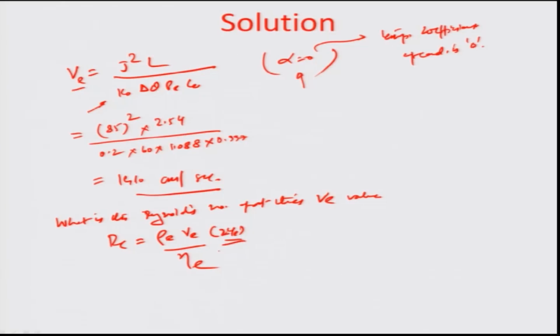In this particular case, you have to understand we are talking about a gap, y for example here, and 25.4, and this is what is going to continue. So, on one side is the tool, another side is the workpiece. And we want to find out what is the Reynolds number in this cross section right here. So, we already have the characteristic dimension as 4 times area by perimeter.